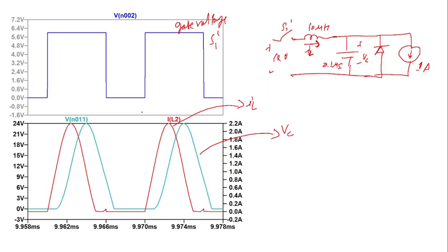Here you can see that whenever S1 prime is turning on, the current starts smoothly. Sorry, let me change the color. The shape starts smoothly, which means this is the ZCS turn on. So here let me write it, ZCS turn on.